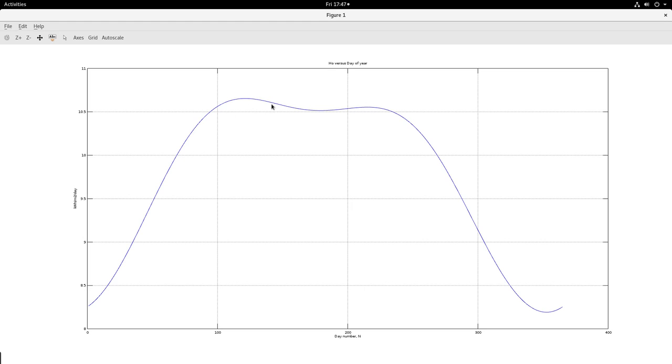So you see that this is the h naught, kilowatt hour per meter square per day, computed for every day of the year, where the x-axis is the day number. So day number is 1, 2, 3, and somewhere here is 80. We had calculated for 80. Remember that it is 10.54, and this is that one single calculation, and so on at 100, 200, 300, 365. These are the values that you calculate for the h naught. This is for a horizontal flat plate collector. This is how it will look like.